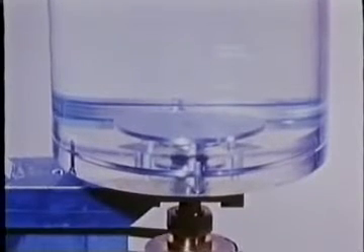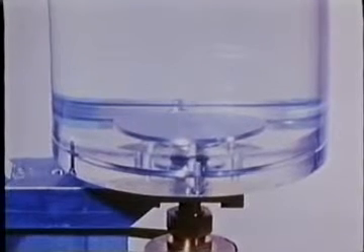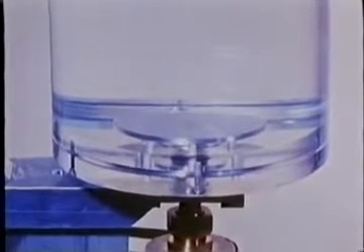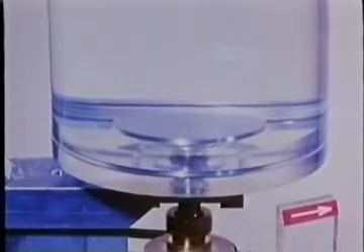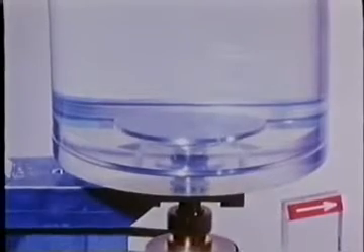This cylinder has a central disc which is flush with the clear plastic bottom. The disc will be rotated at a slightly smaller speed than the cylinder. Ink has been injected through a central hole in the solid lid, which is in contact with the fluid. The interior fluid, out to the disc radius, adjusts to a rotation speed halfway between that of the disk and that of the upper lid. The accommodation to the no-slip boundary condition occurs in an Ekman layer on the disk and another Ekman layer under the lid. The fluid in the outside ring almost rotates with the cylinder.